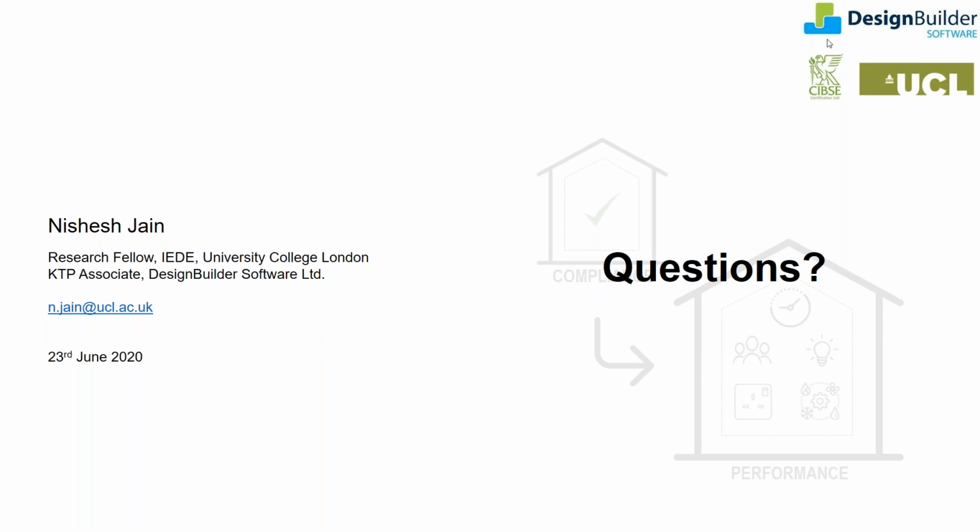Once you have created a calibrated model, you can compare the model settings. You can see what settings you put in the TM54 model and the settings you have in your calibrated model, and that can give you an idea of the root causes of those deviations. Then you can run scenario analysis on a calibrated model to see how you can minimize those and reach a better operational performance throughout. So this is where weather comes in, and weather is very critical here. You cannot practically use generic weather files when doing a calibration model. So that forms a good part of it. I hope that answers the question.